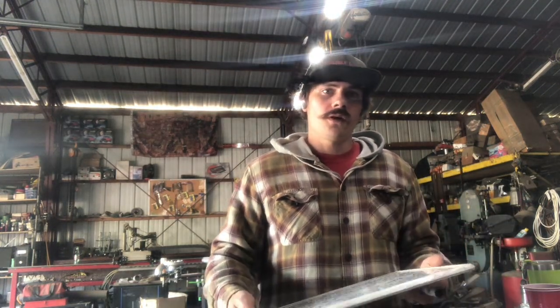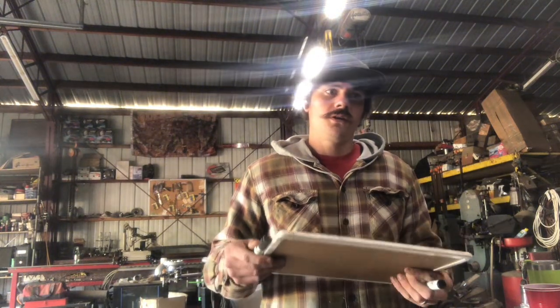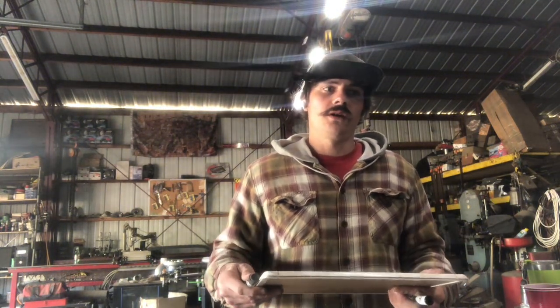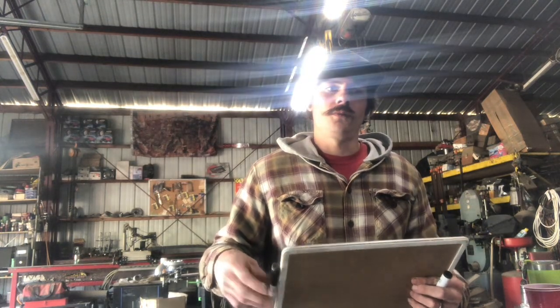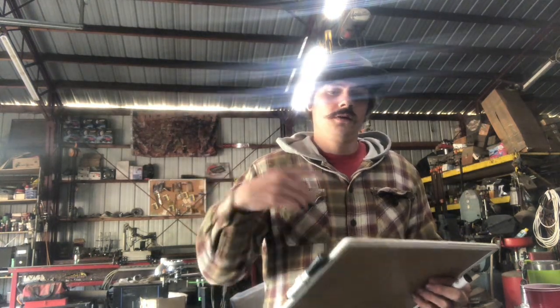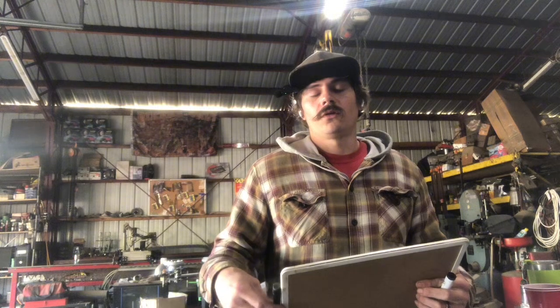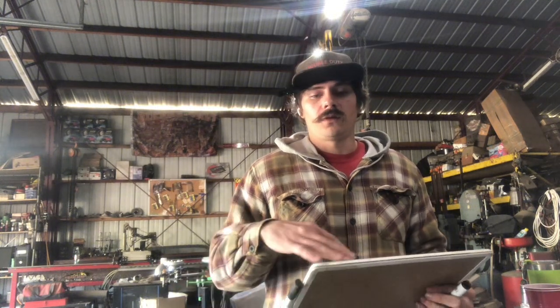There are cases where it's higher with really, really big turbochargers because the area finally gets large enough. And smaller turbochargers tend to incur this issue at lower expansion ratios, because the curtain area of the nozzle and the area through the turbine wheel is smaller, so their rate of climb and your P1, P2 overall speed grows a lot faster with the same mass flow.